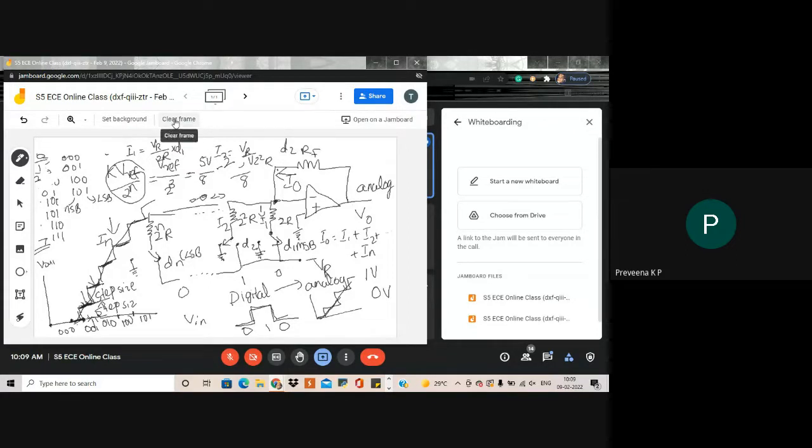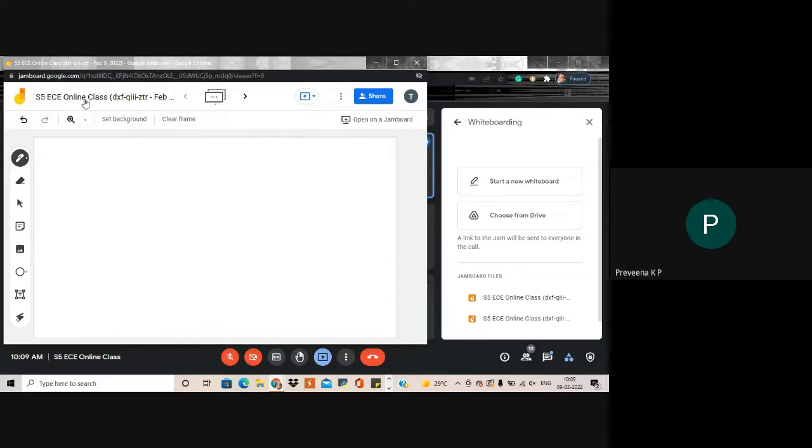So I am simply clearing all this. Just we can start writing the equation. I0 equal to I1 plus I2 plus etc. plus IN. What is I1? I1 is equal to VR into the bit value D1 divided by 2R. What is I2? VR into D2 divided by 2 square into R. Similarly, it will go up to IN, that is VR into DN divided by 2 raised to N into R. So this is our equation.